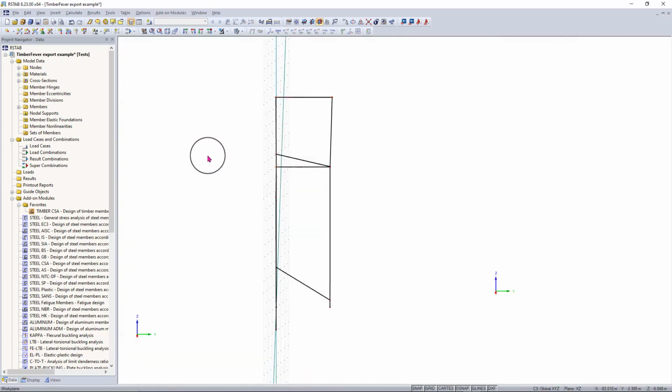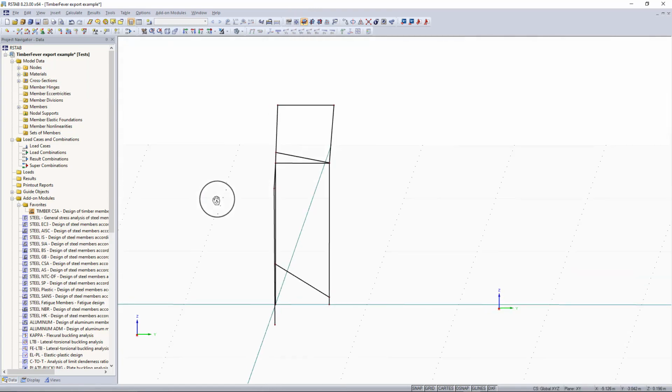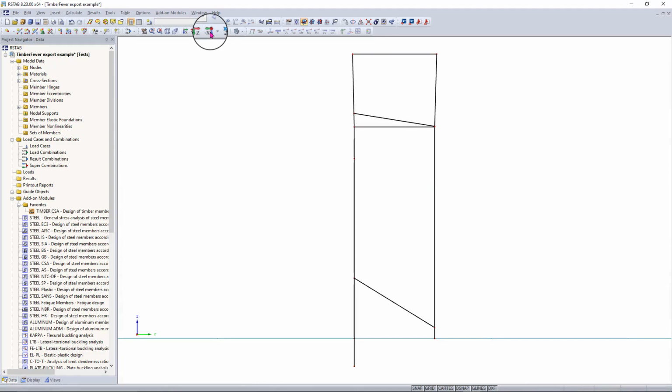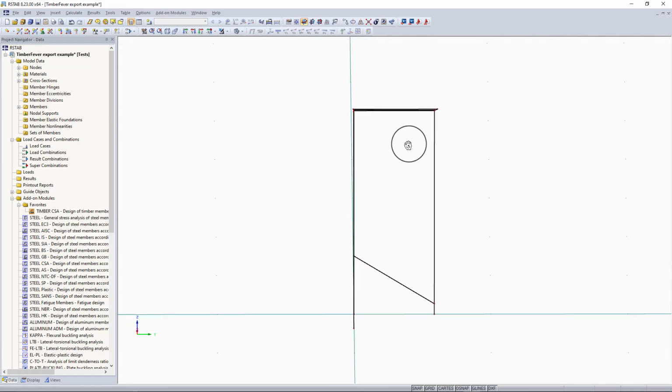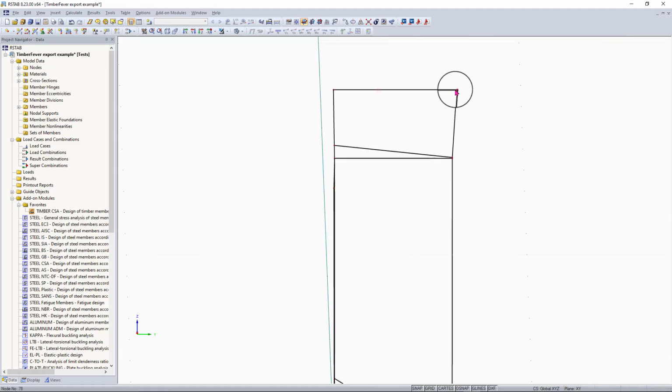We also want to make sure it's completely square here as well. So what we can do is go up to our workplane here, the XZ workplane. We can switch that, and we can look at our reverse X direction again, and you can see that this is not a square, so we can hold Control, and then we can rotate this, and you can see that these nodes here are not completely lined up in this direction either. So what we want to do is change the location of these two nodes to match the location of these corner nodes here.